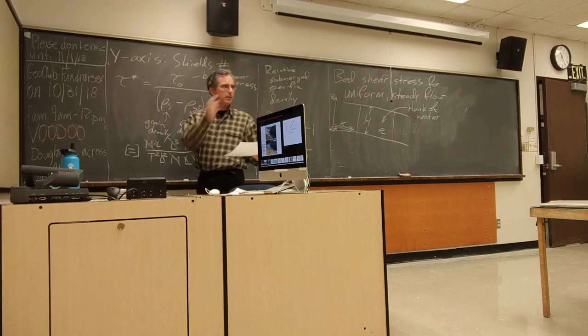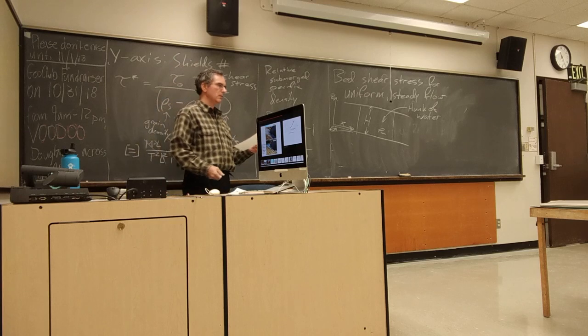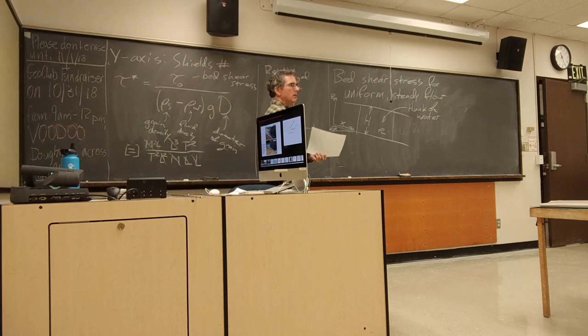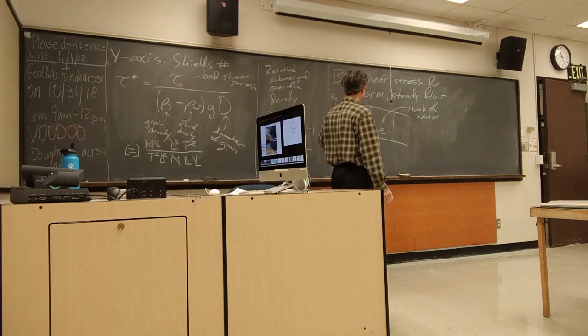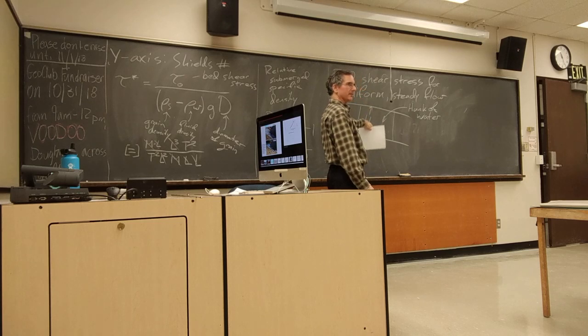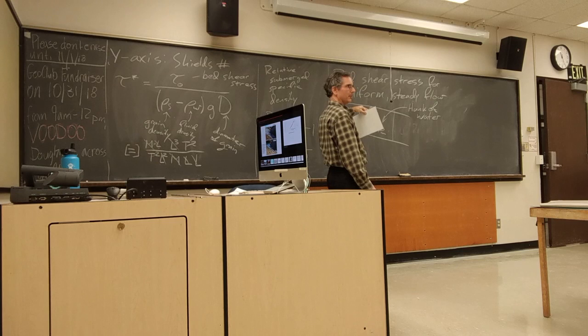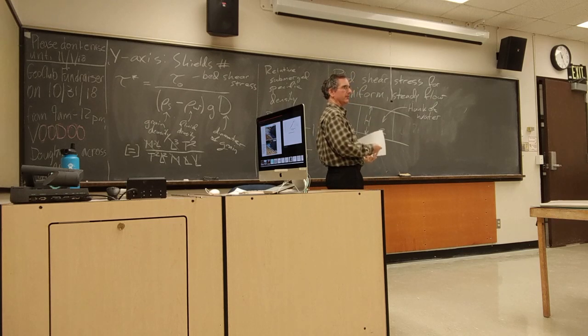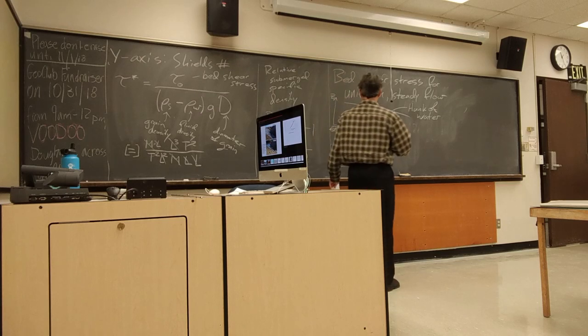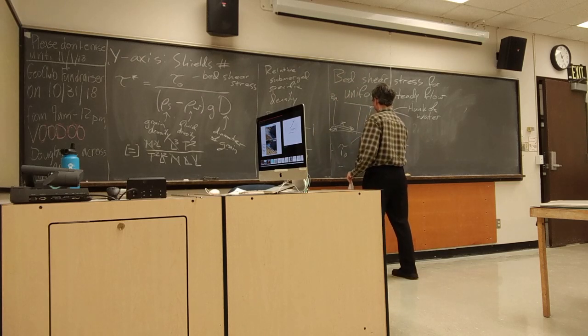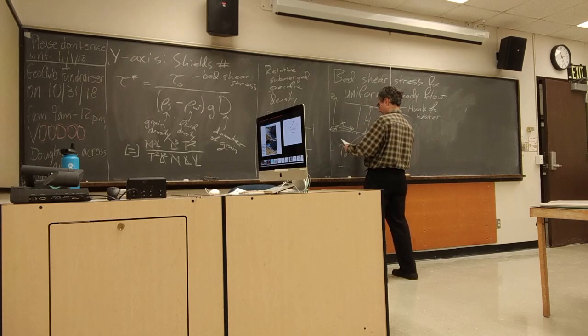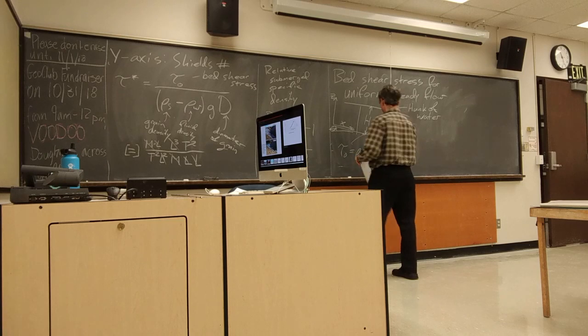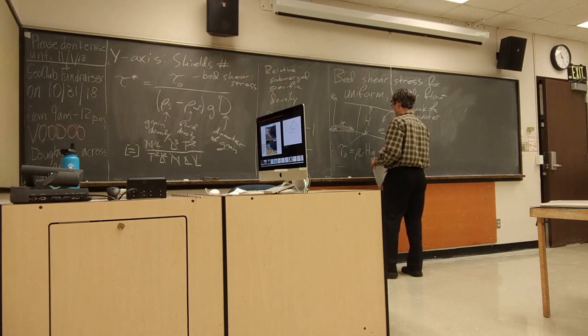Now, I have a quick question. Is this talking about water flowing over, I guess, just sediment down a hill, or are we talking like rivers and streams? Yes. All of the above? Yeah. Okay. All of the above. Now, I hope that I don't need to go through this again, because we're going to use the same formula for shear stress that we use for glaciers, that we use for landsliding. That is that my bed shear stress here is just density of water times the thickness of the hunk of water, gravity, and sine of the slope angle.